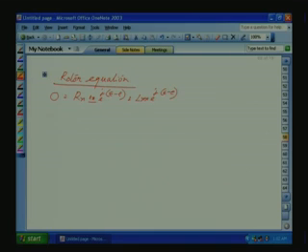This epsilon minus rho will transfer all the rotor voltage and current equation defined with respect to the rotor axis. It will be transferred to the dq axis. d by dt of IR e raised to minus j epsilon.